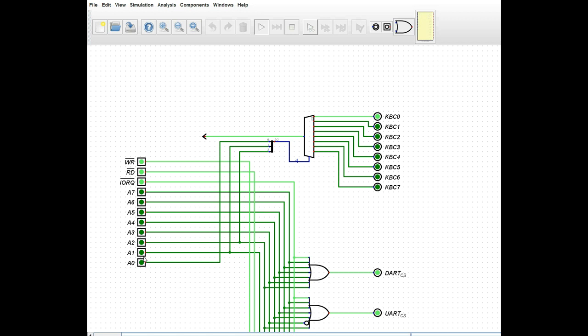And the reason for that being is because for every single component that you have in the line, I guess you could say in the daisy chain of items that you have to have active in order to either read or write your signal, timing becomes an issue. So we want these to go high or low as quickly as possible. That way when we read, because we're not going to be writing, but when we read from it, we want that value to be present as quickly as possible. We don't want to have to wait. And that's essentially what we've done here.